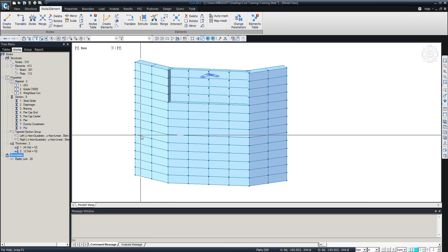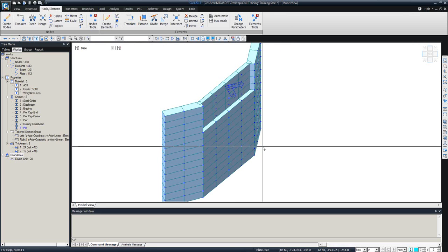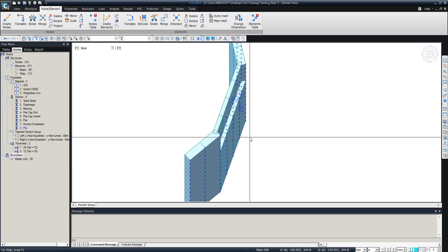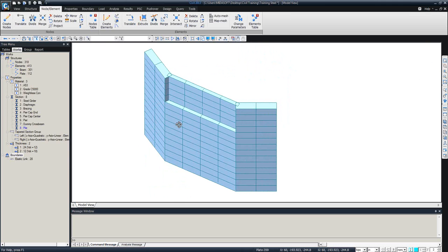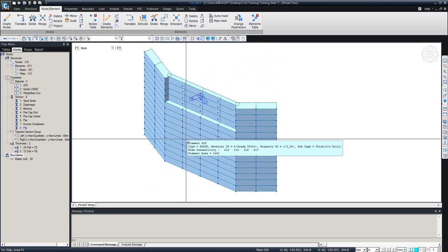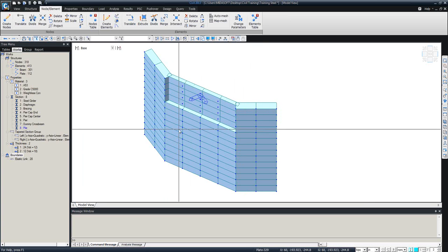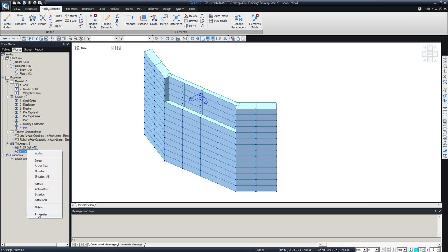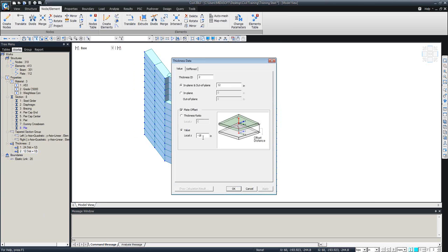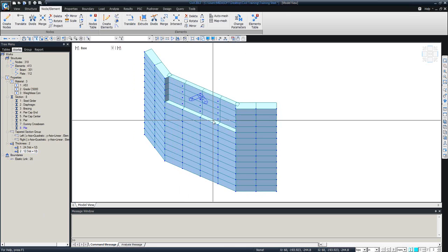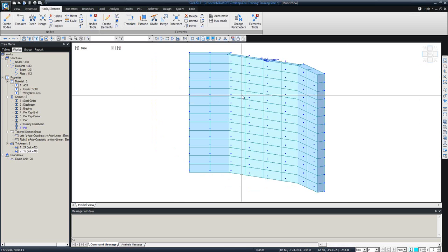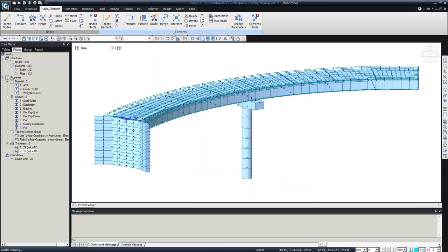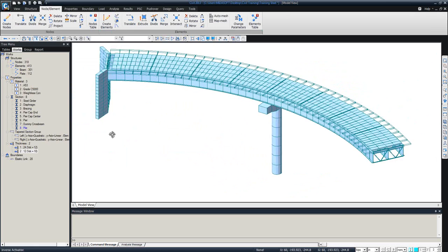It automatically converts it. As you can see, I adjusted the offset option, because the same concept that I showed you for the girders or beam elements, we have for the plates, where you can just simply apply the plate offset. So you can just adjust the location of the plate with these offsets. All right, let me see what we have. Activate all. All right, so far so good.